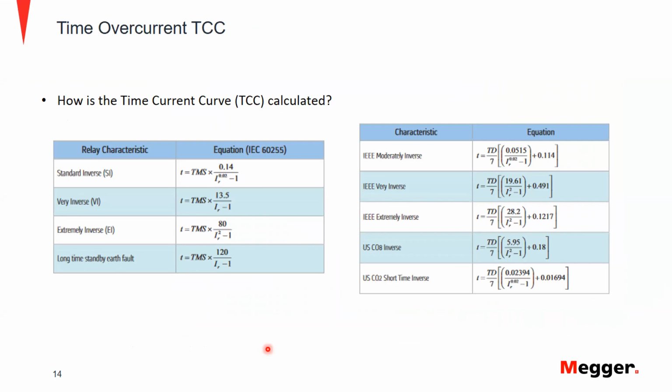Okie doke. So Mohit, next question is going to be for you. What is the difference between TAP and PSM? Okay, so TAP and PSM both are used frequently for electromechanical relays and sometimes for solid state relays. I have not seen them being used for the microprocessor relays.